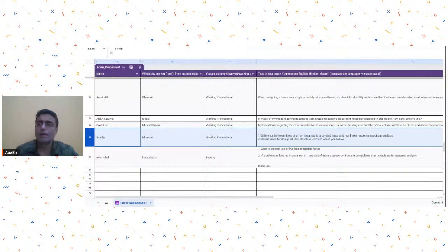That means my material will have a uniform stress strain curve within the range of stresses where we are doing the analysis. When I talk about nonlinear, that nonlinear may be due to geometric nonlinearity, and it may also be due to the material nonlinearity. Okay, so that is what I would mean by linear and nonlinear analysis.